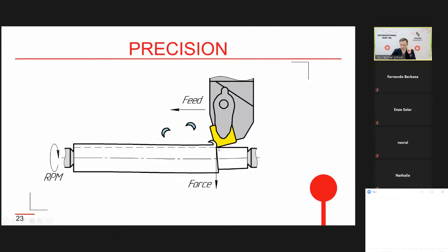It's an ideal process, but really, when the process of cutting starts, it means that we have a force acting on the workpiece, and from physics, you know that the same force will act on the cutting tool. But the workpiece is not rigid, or the rigidity of the workpiece is low. That's why this acting force will bend, will deform the workpiece. And you can see here that the workpiece bends in a way like a smile.